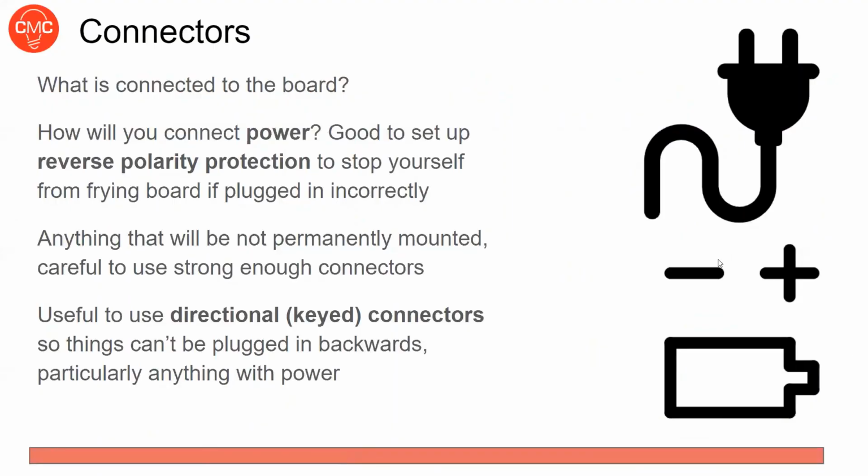So this is just a quick overview of things that might be useful to think about before you even start. And again, this is just electrical considerations, but then talk to your mechanical engineers, talk to your software engineers. Your software engineers need a certain amount of memory or a certain technology to program the firmware onto the microcontroller. Your mechanical engineers need to maintain a certain power, or need certain components, or have thermal considerations. You need a heat sink on your board, that kind of thing. So talk to other people on the project. If it's just you and you're doing a small project, just think about all of these things before you even start drawing up a schematic, before you pick actual components.